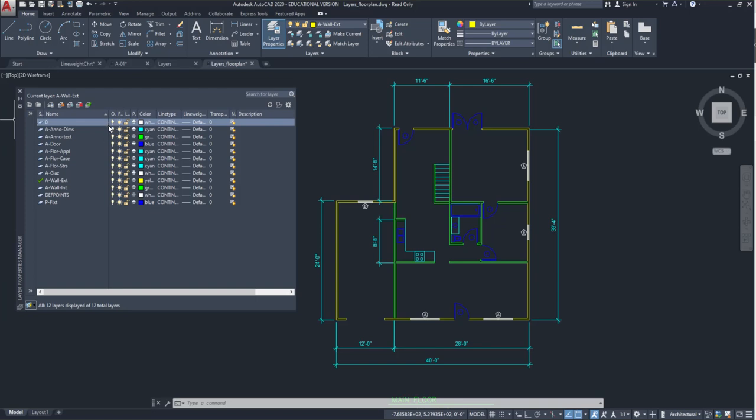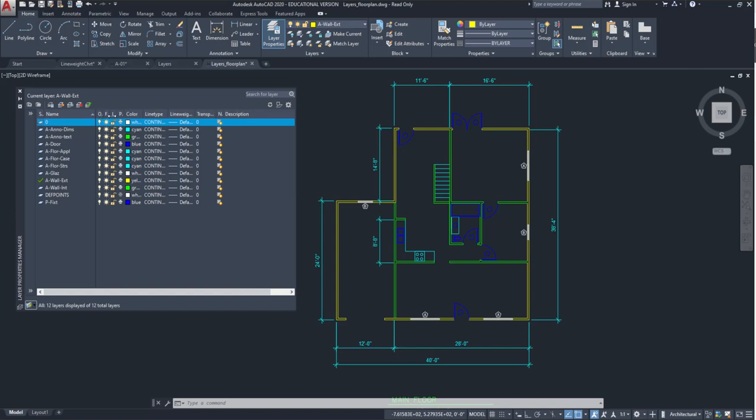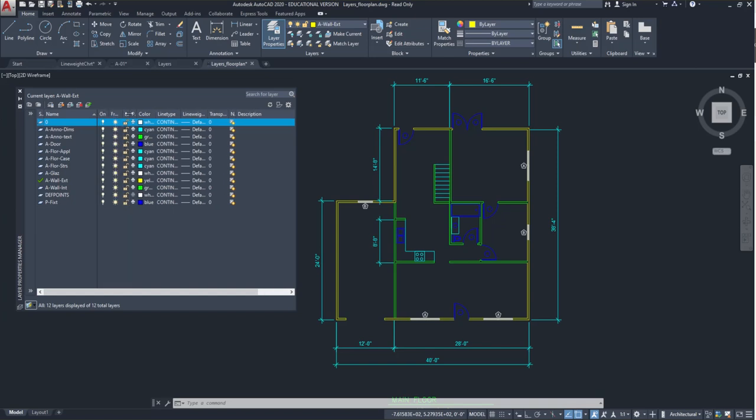That looks good. The first thing I have over here is the name of the layer in the drawing, okay? So here's the name. I can change the thickness of this and all these other little categories just by clicking in between them, just like Excel, right? And I can make them larger, smaller, whatever.